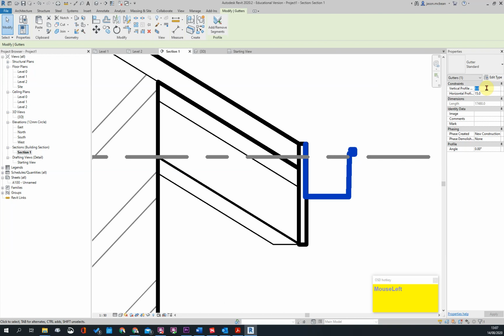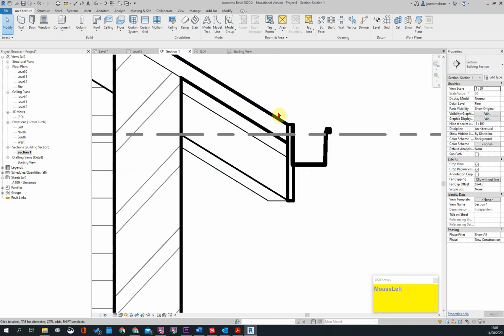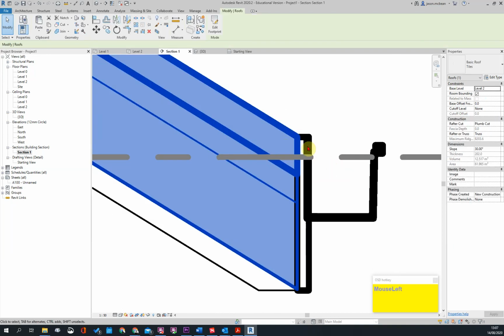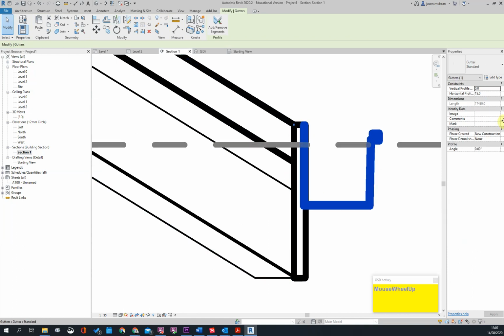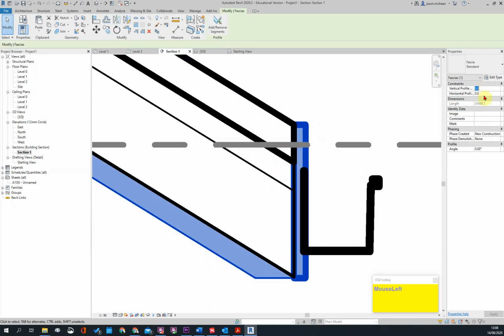So when you cut a section through, and it's an object that you never see, you never really see it other than through a section. So if you're taking 3D views and all that kind of thing, you don't model it. That's why I use Revit's families to kind of give me this information. Okay. And there's a technique, I'll show you how I draft in this. So this will have to drop, because this will drop minus 50, for example, because that's where, so maybe minus 70, because this sits beneath this top layer over here. Okay, so does this. So this horizontal offset minus 70, for example.